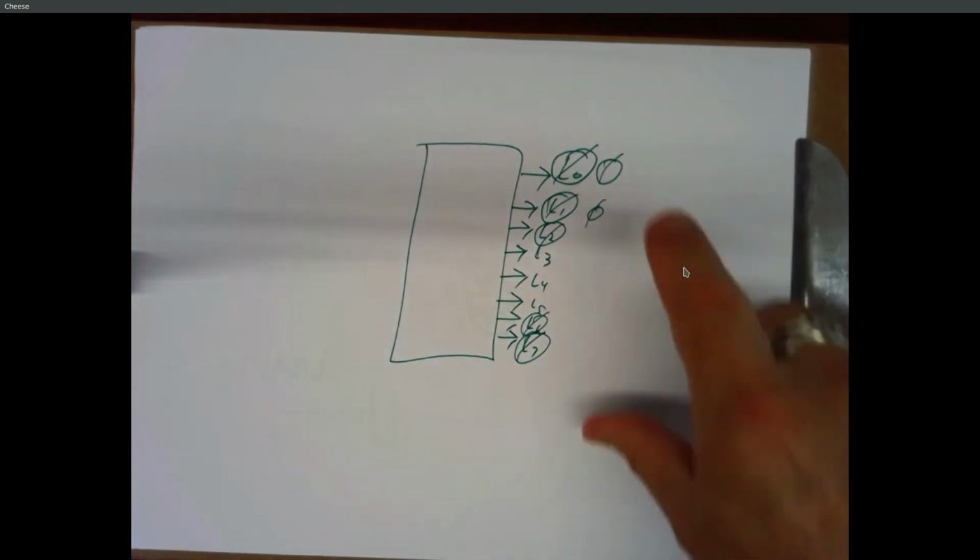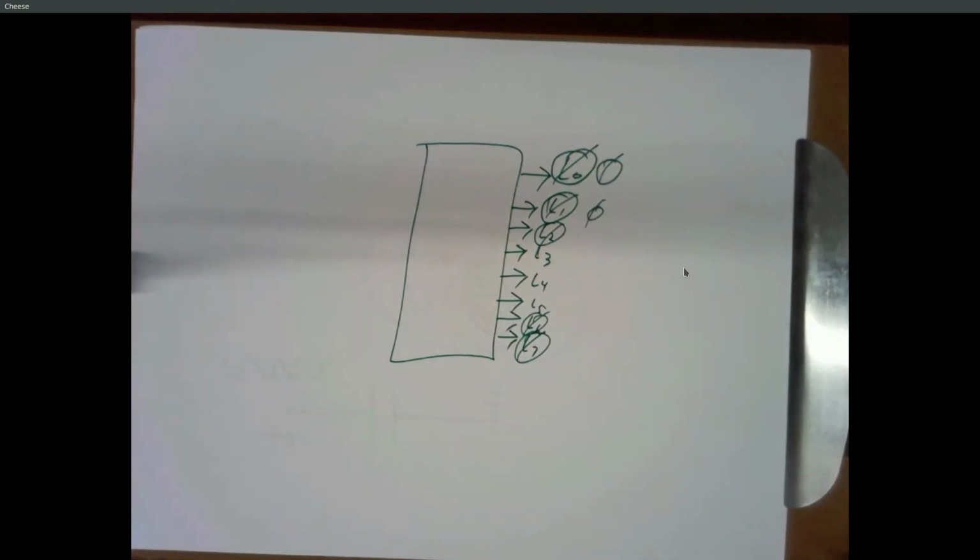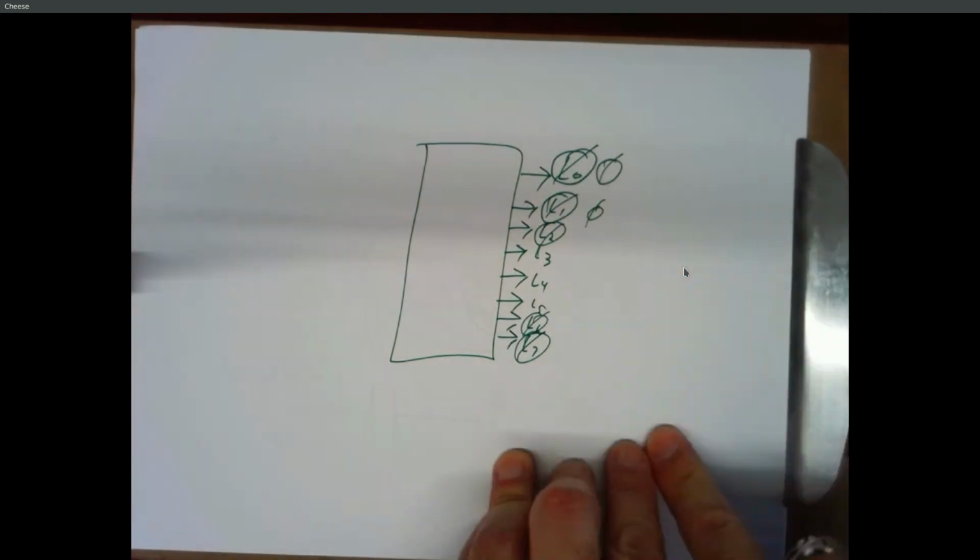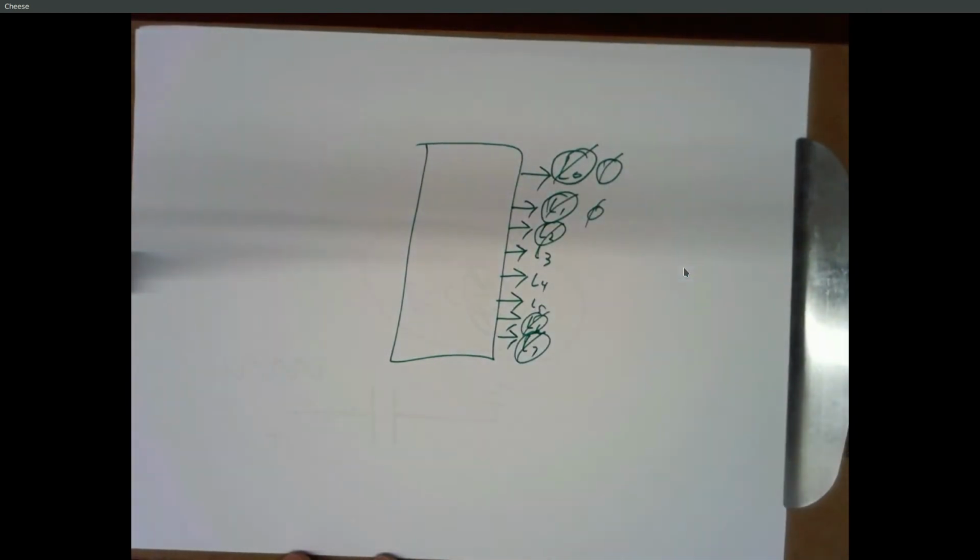And if you don't try to lay them out in order, that's what's going to happen, because the wiring on the chips is always wonky, right? It's not necessarily in order. So put your LEDs somewhere in order and then connect to the right pins using wires. Okay, and that's just easier to do up front than changing it.